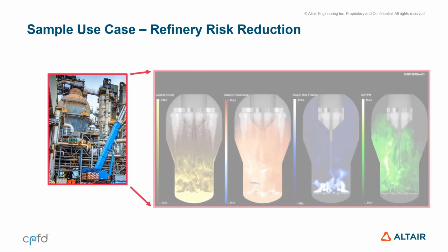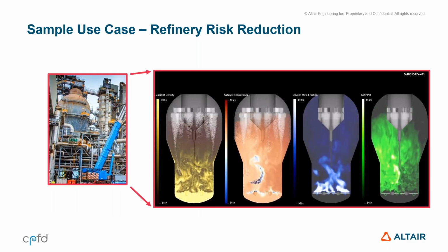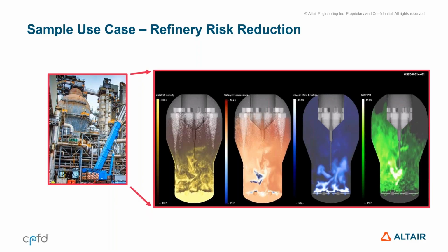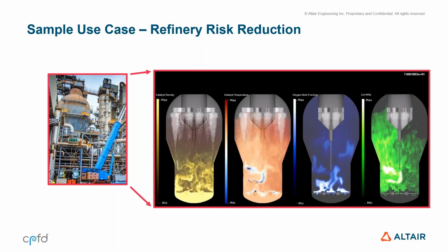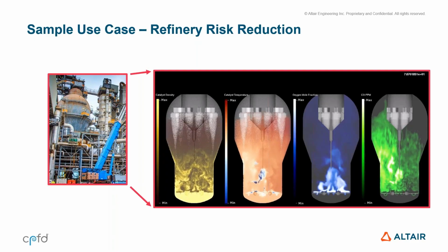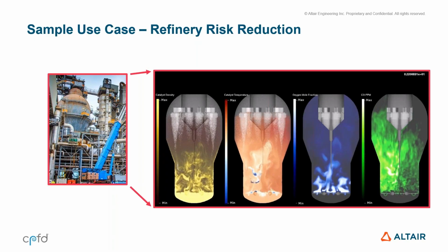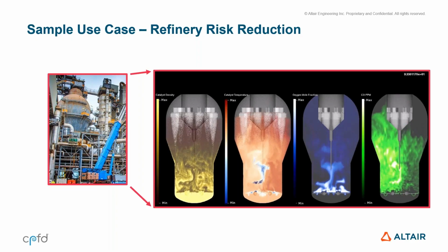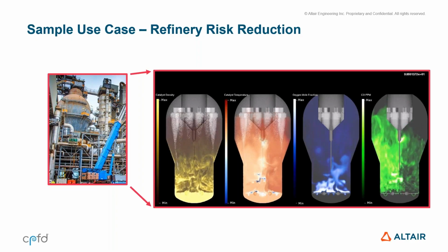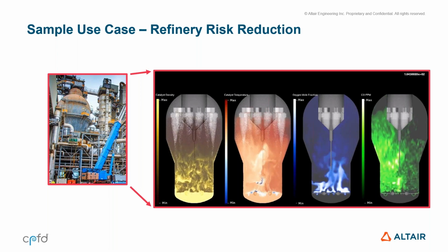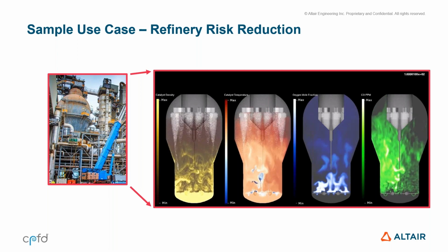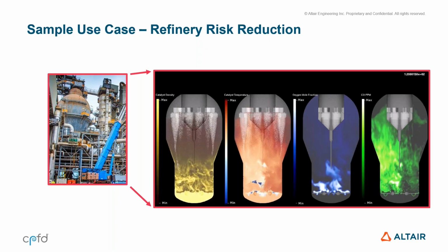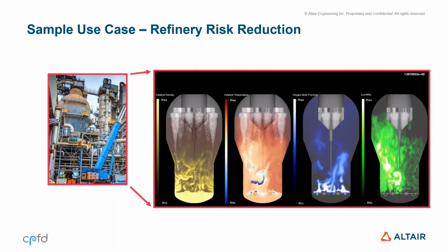The Barracuda Virtual Reactor model of the regenerator was used. And again, you're seeing on the left, the gas particle motion. Second from left is the temperature. There's some non-uniformity there. The blue-white there is the oxygen utilization. It should be burning up all the oxygen in the unit. And it should be a full burn unit, so there shouldn't be any CO leaving. But when we're looking at where's the concentration of CO still present, the green on the right shows that. And what we see is this asymmetry. And I won't go into all the technical details.